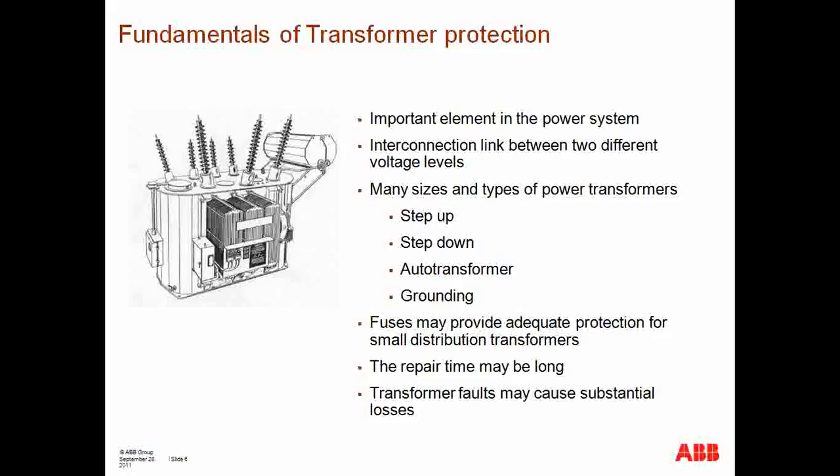One case would be in generation. Perhaps you have a generator that you want to connect to the transmission system. Generators, because of design constraints regarding insulation and personnel safety, cannot have ratings of very high voltages. That's why generators typically have rated voltages on their terminals below 13.8 kV. But as we know, transmission systems are typically in the order of 115 kV and above. So if we need to interconnect those two systems, one in charge of delivering power and another in charge of generating the power, we need a transformer, which will in turn connect these two systems.